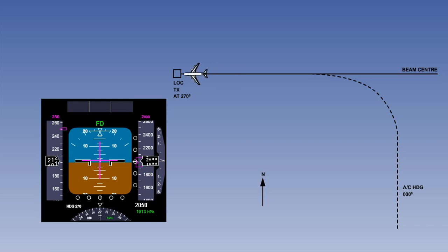The flight director adjusts the flight director bars, which can then either be followed by the pilot or, if engaged, the autopilot. The flight director system has the aircraft performance parameters stored in its database, and with the input from the air data computer, it will never command a maneuver which could overstress the aircraft.